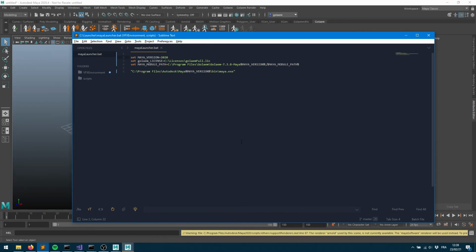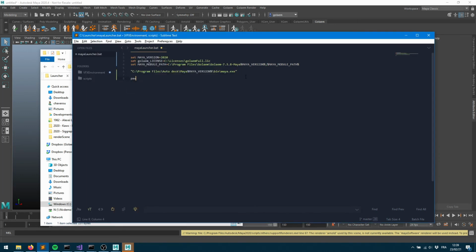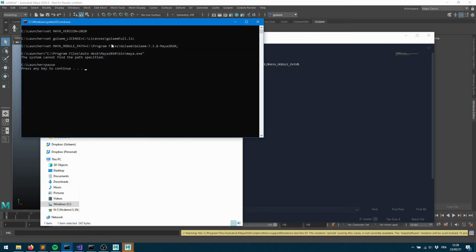And I also wanted to show you something. Let's say for some reason you made a mistake, maybe in some path, and you're not really sure what's going on here. So here the path is not correct. When you launch the launcher, you don't get anything. If we had bionic eyes, we'd probably see the command window pop up and display an error, but we don't have the time to read that error. So what you can do is, at the end of your script, add an instruction called pause, and save. And whenever you now launch your system, rather than closing right away, the window will pause. And now you can evaluate what's going on here.